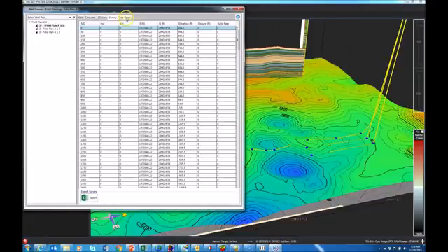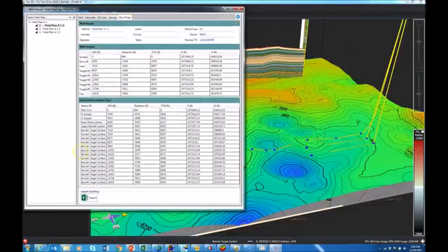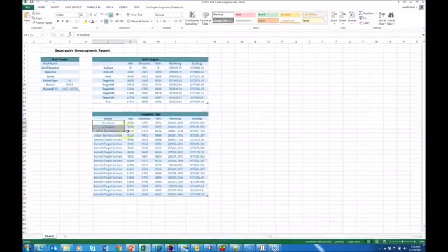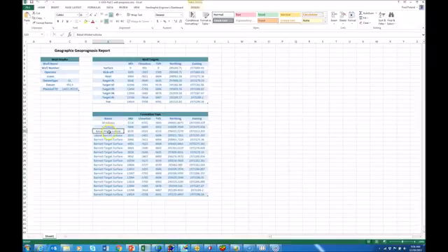Next, let's look at the Geoprognosis tab. This will generate a geoprognosis for you that you can also export to an Excel spreadsheet. And it will give you a prognosis of where you expect to penetrate the surfaces: the M surface, the LS surface, the basal Atoka, the upper Barnett, and then the Barnett target surface is encountered several times as it porpoises down the horizontal reach of the well.